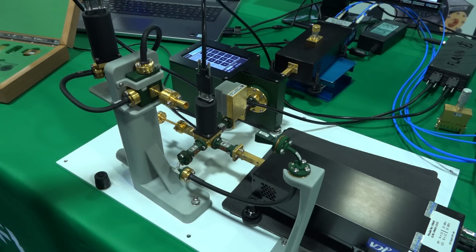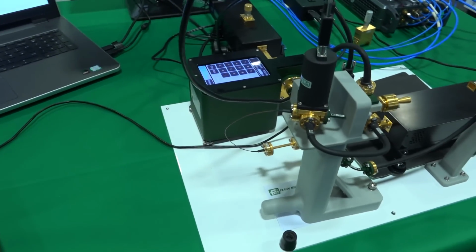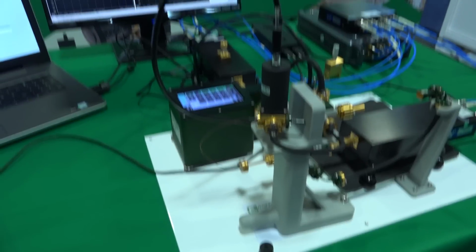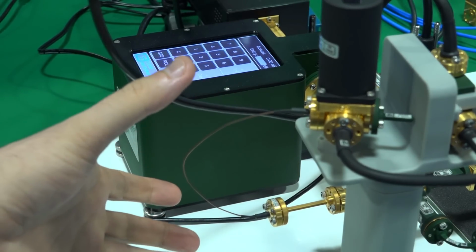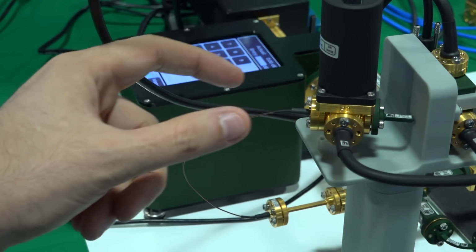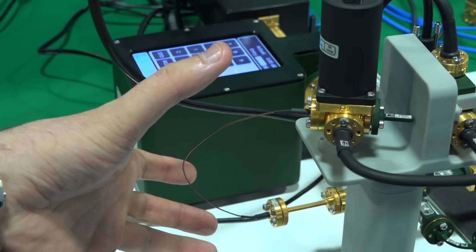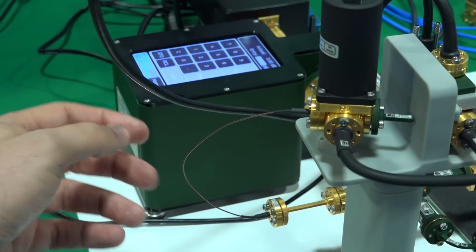And in fact, if you go to higher frequency, you would want them to be even more compact, because as you can see how closely coupled this setup is. And they have another piece here, which I actually never seen before. Here they have a coaxial cable that has a direct transition to D-band. But this is a full 110 to 170 gigahertz coaxial transition. There's no connector. These pieces come out together. In this distance, you're talking about 5 or 6 dB of loss, but I mean, this is super flexible and thin. I've never seen something like that.